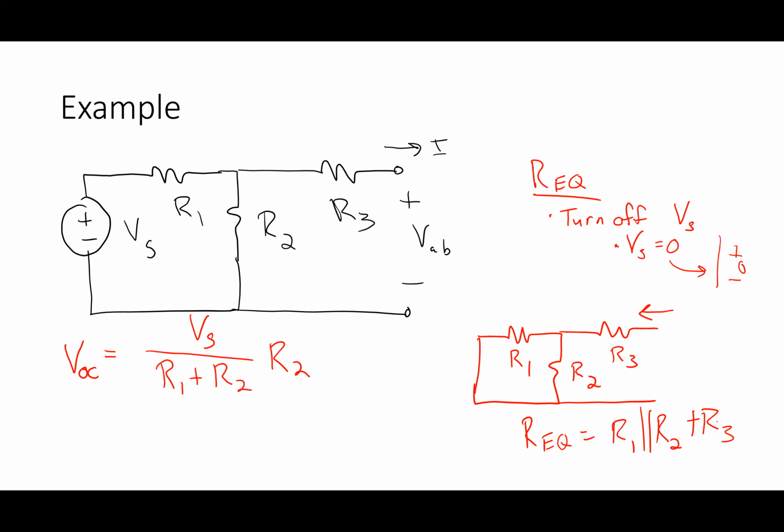How is R1 parallel with R2 if they share the same current? R1 and R2 do not share the same current in this circuit. This is a question people always get confused by. When I was calculating VOC, looking at the circuit on the left, there is no current flowing through R3, and R1 and R2 are in series.